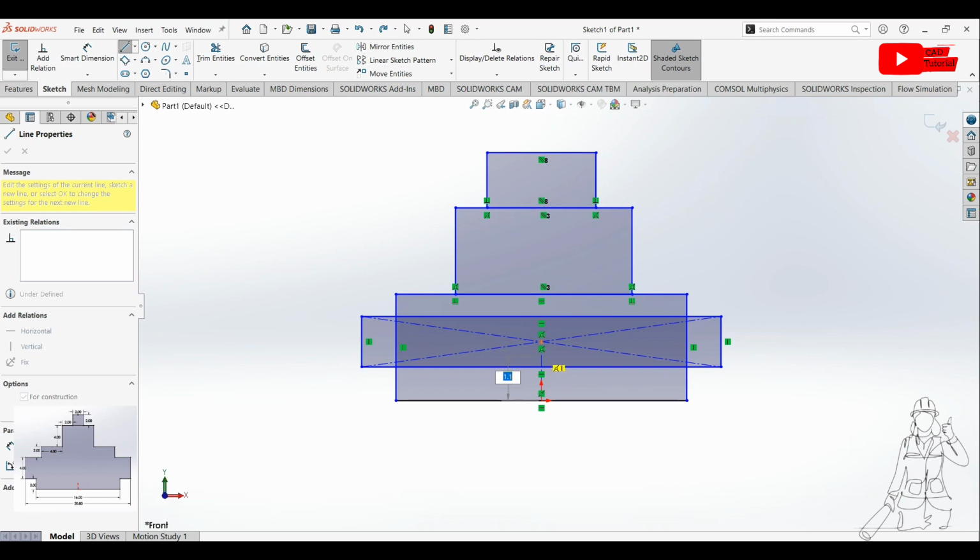Since we are creating the center line, note that we can move the line endpoint slowly at an angle until the vertical relation, you see, appears, at which point you can lock it on that. This is one way in which SolidWorks interprets the relations we want to apply and applies them for us. We can use this approach to make sketching faster.